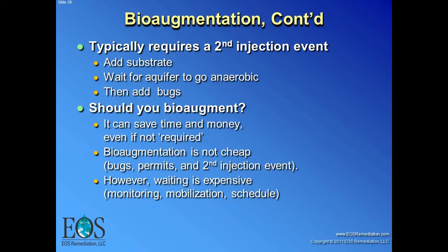But if they're present, even at pretty low numbers, or they're absent completely, we'll almost routinely bioaugment. It just saves time, it saves money, and in the end, you get a good product. It may increase your cost a little bit, but people don't like failure. And this is that sort of extra insurance that makes sure your project goes well.